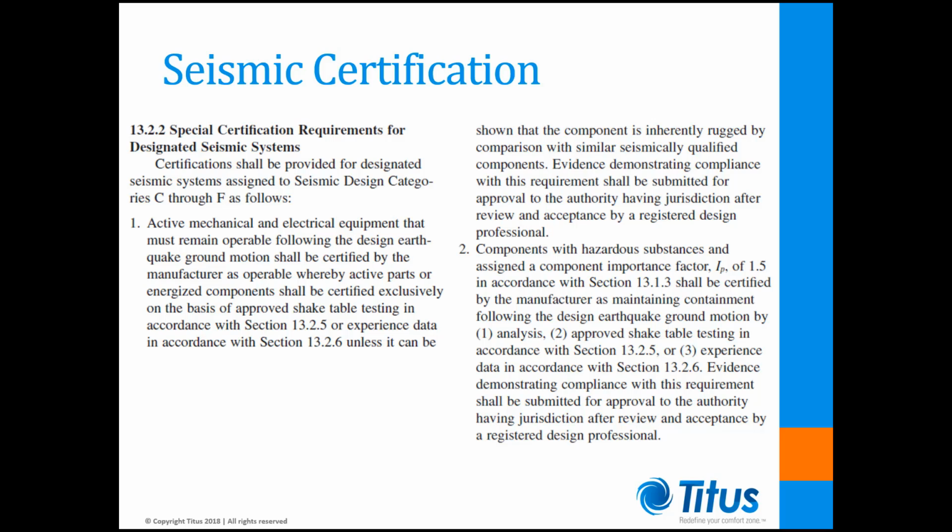OSHPD has a list of pre-approved seismically certified equipment and the proper installations that have been tested to AC 156 to ensure compliance with both IBC and OSHPD requirements.